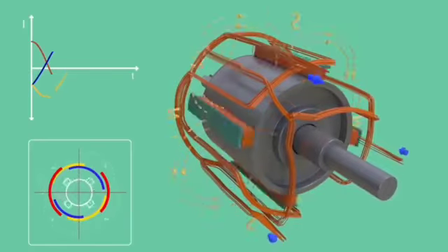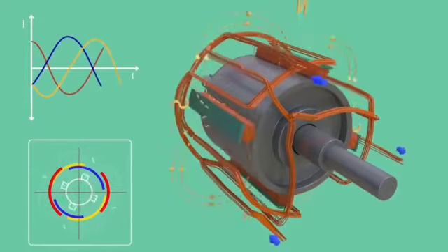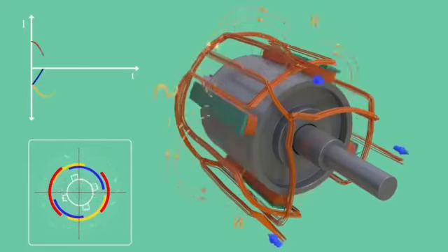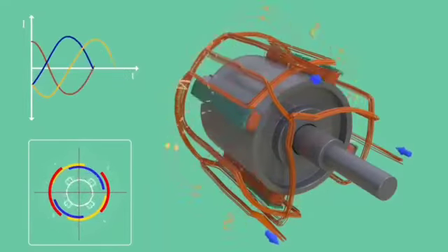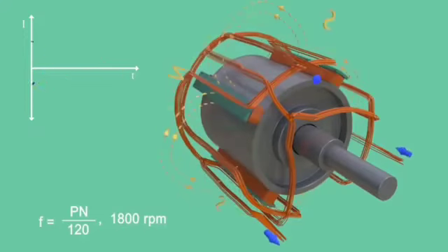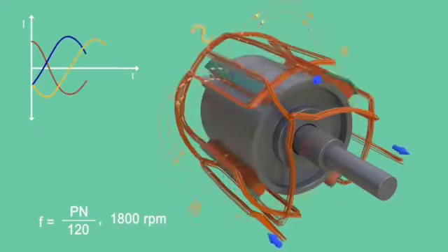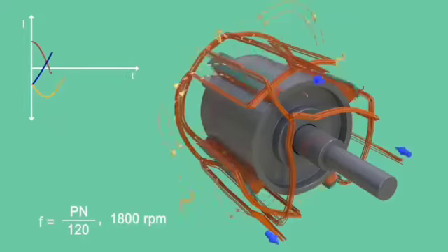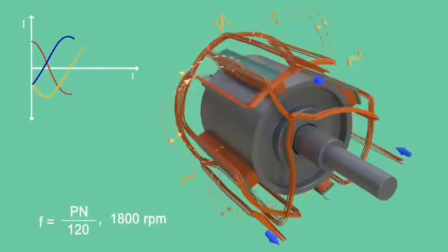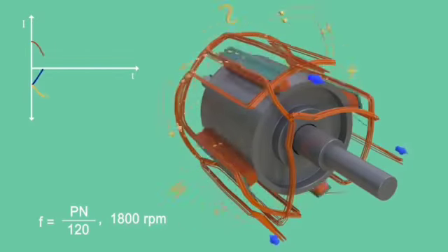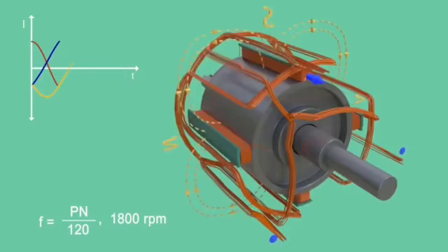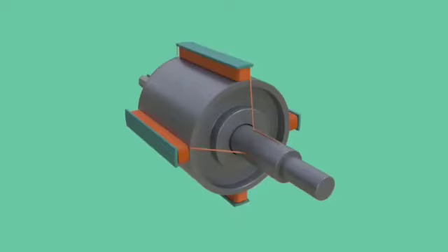It is clear from the equation above that in order to produce 60 Hz electricity, a 4-pole rotor should run at a speed of 1800 RPM. Such huge RPM will induce a tremendous centrifugal force on poles of the rotor and it may fail mechanically over time. So salient pole rotors generally have 10 to 40 poles, which demands lower RPM. Salient pole rotors are used when the prime mover rotates at relatively lower speed, 120 to 400 RPM, such as water turbines and diesel engines.